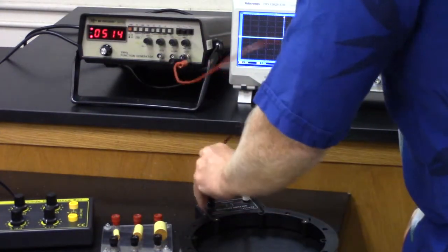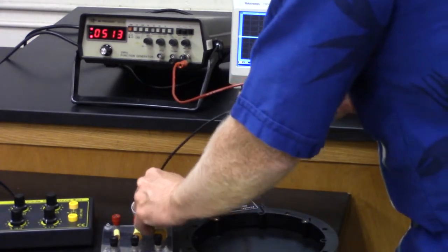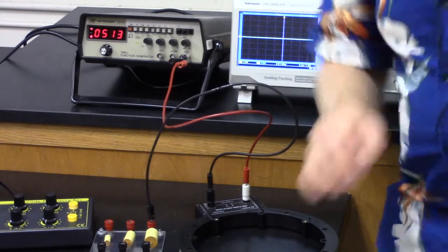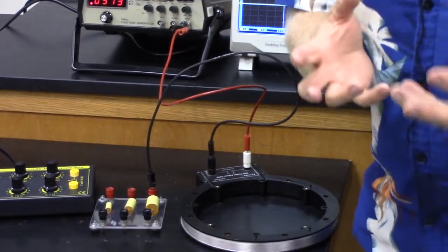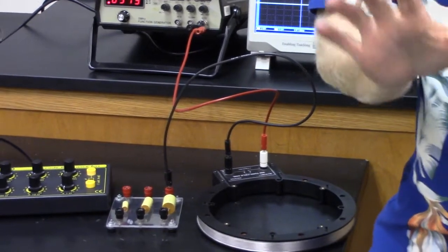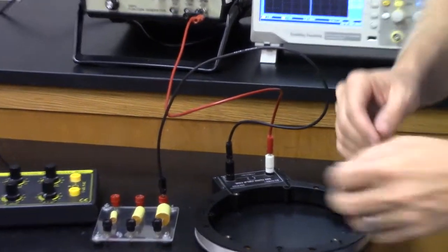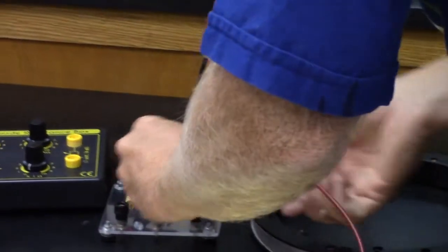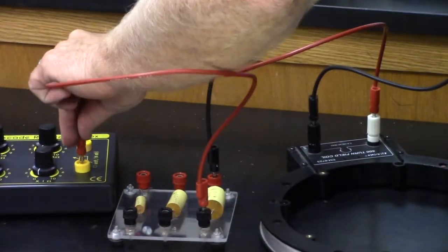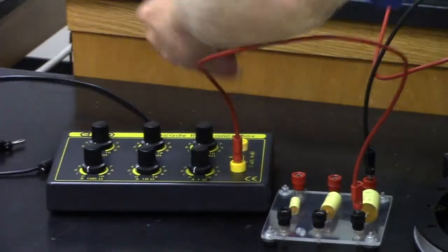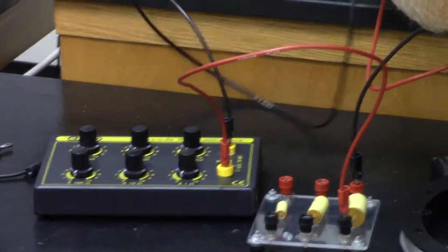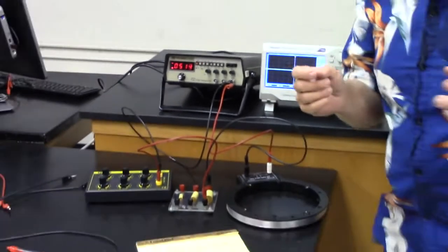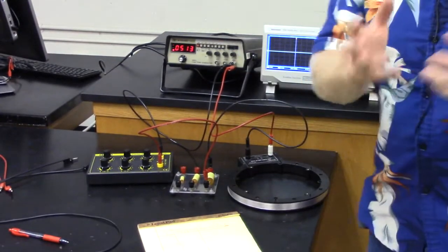Okay. Then following that chart, it says go from the inductor to the capacitor. And I'll feed it into this big capacitor, which says on the side of it 1 microfarad, and we'll eventually measure it. So don't take that as exactly the number, but that's going to be pretty close to what we get. Then we'll feed it from the capacitor to the 10 ohm resistor, and then from the 10 ohm resistor we complete the circuit. So there's my AC LCR circuit.